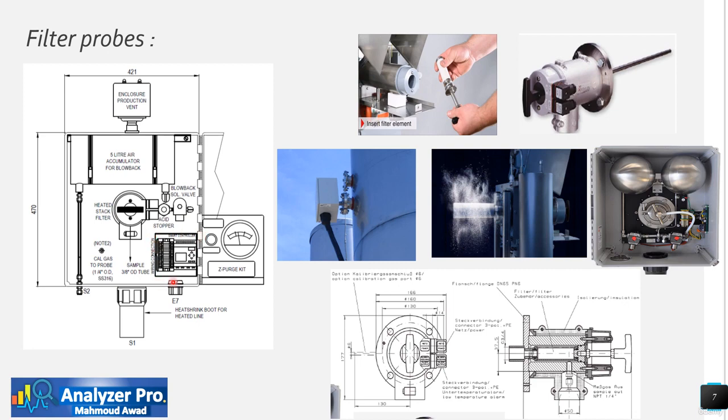Note that the blowback gas should be above the dew point to prevent temperature condensation in the sample lines or filter probe, and must be compatible with the process stream.